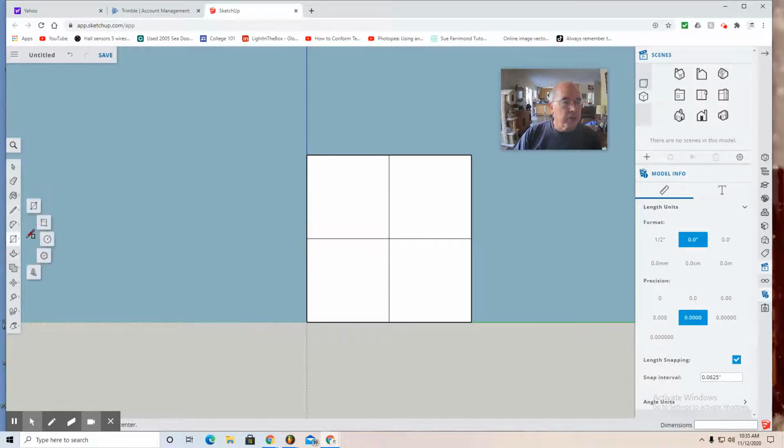So then I'm going to return to the circle tool here and click and enter a radius of 0.125. Look down at the bottom right corner, you can see radius. I've entered 0.125, and then I just hit the enter key. Oops, maybe not. Here we go. Enter. Maybe not. Nope. Control Z if you mess up. 0.125, enter. There. Now I have a 1/4 inch.